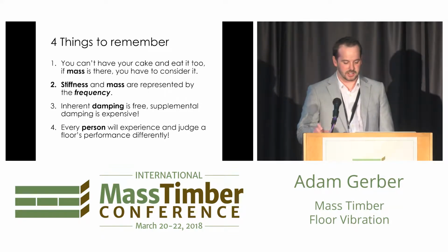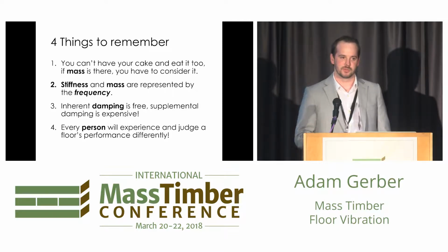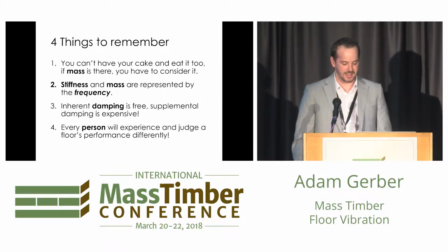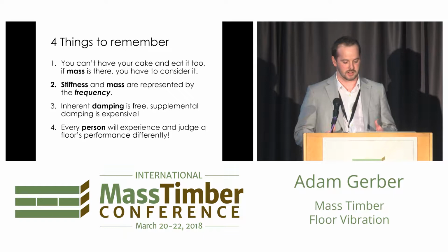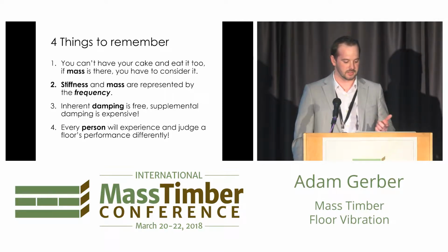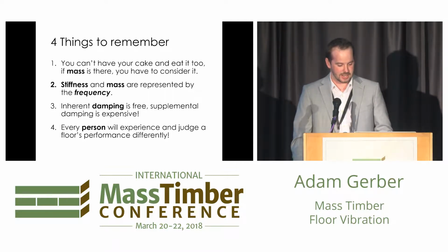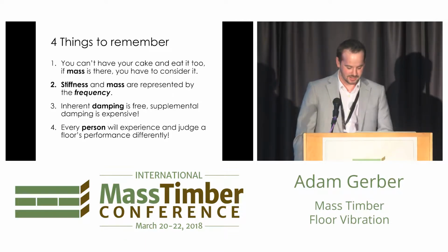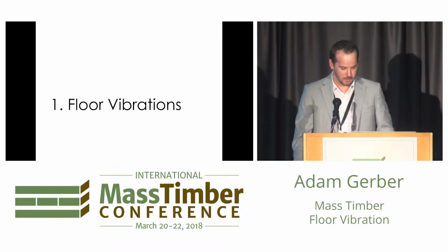So 4 things to remember. You can't really have your cake and eat it too. A lot of people just say, as a blanket statement, just add mass, it'll go away. If mass is there, you have to consider it, and we'll circle back on that a little bit later. Stiffness and mass are represented by the frequency. So when you're talking about the frequency of a floor, you're inherently talking about the combined properties of the stiffness and the mass, and vice versa. Inherent damping is free. Supplemental damping is really expensive. And every person will experience and judge a floor's performance differently, so it's a moving target, which is awesome.